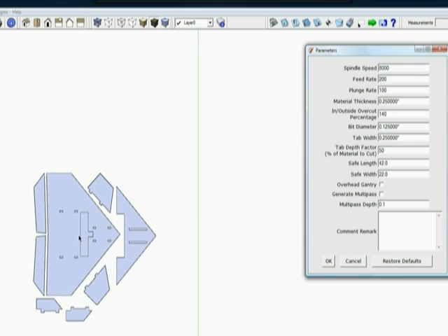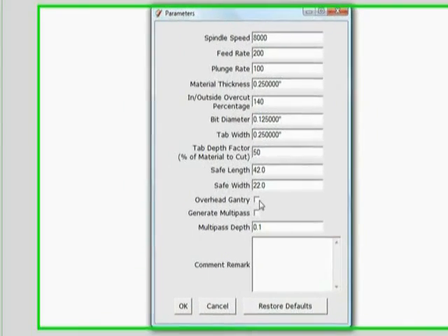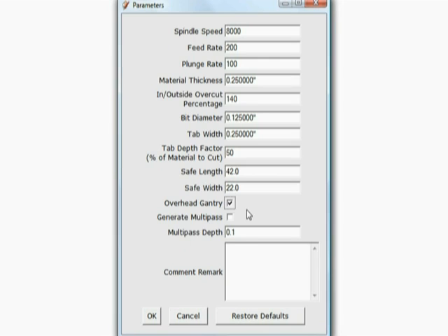Well, when we try to use PhlatScript with overhead gantry machines, like the new PhlatPrinter 3 that's going to be released very soon, or maybe I want to use this script, as I often do, on my overhead gantry commercial type machine, then I needed to be able to invert those particular directions of cut. So this gives us that opportunity. If I have an overhead gantry machine, I would check that, and that's going to set it correctly: an outside cut equals this cut direction, and an inside cut equals the opposite of that cut direction.